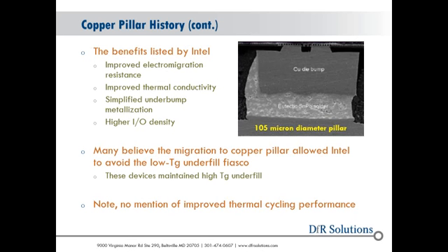And we're going to talk about that a little bit, but the introduction of a copper pillar may or may not improve thermal cycling performance, and in fact it may even degrade it depending on a variety of parameters. And that's actually one of the initial motivations for this talk, really trying to understand what copper pillar does in terms of thermal cycle reliability, because that's really, if we think about it, one of the biggest problems with flip chip, right?